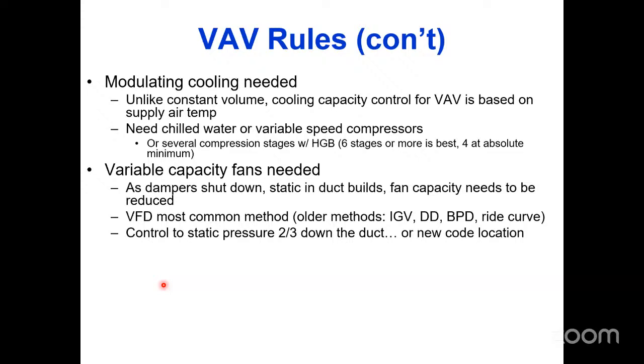The way you should do it is you should put that pressure sensor at the VAV box that's the furthest one away, and as long as you can get enough pressure there, everybody upstream is going to get enough pressure. The problem is no one wants to run the tubing all the way over there, and I don't even know which one's furthest away. It's not geographically the farthest, it's the one with the biggest pressure drop duct run. I don't know which one it is. And I also got a run going to the left and to the right when it comes down to the building. So I don't know.